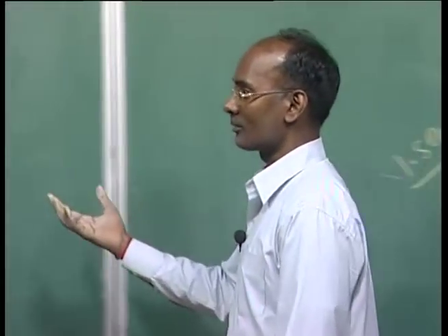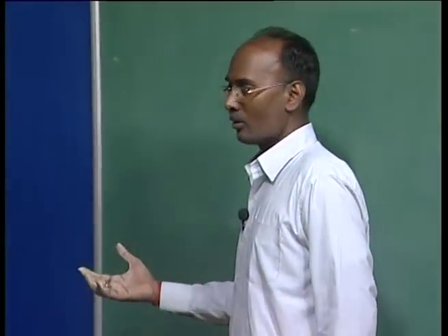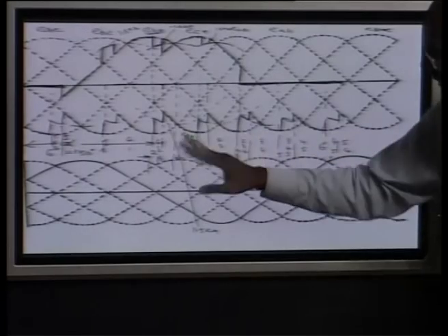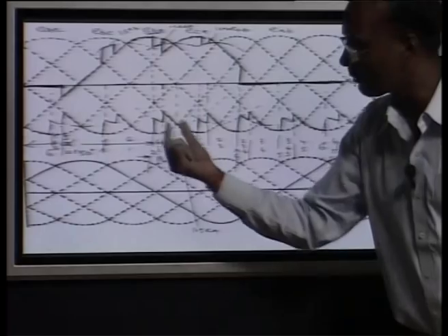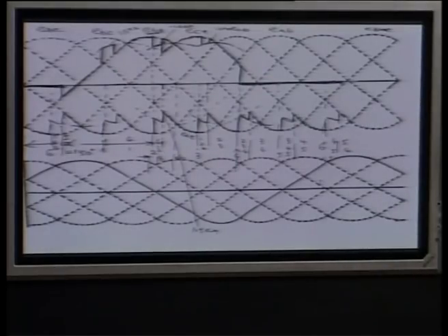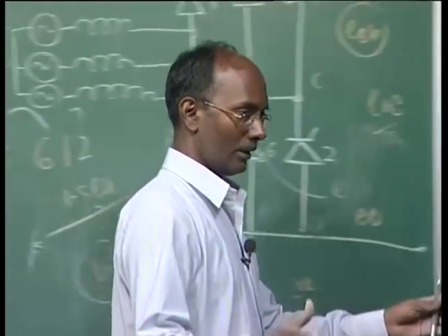Now you can see it is so simple. You just have to monitor which valve is conducting and what the voltage will be, and you have to be careful here when 3 valves are conducting. This was asked of you, and this is the problem I mentioned, so you can go ahead with this. Is it clear?